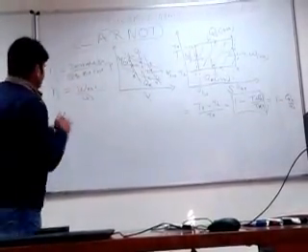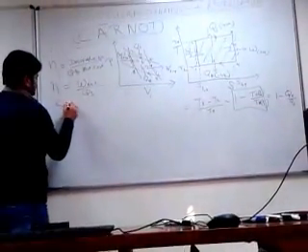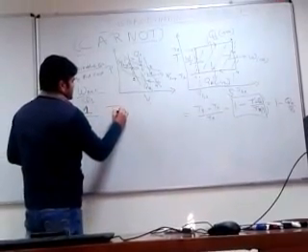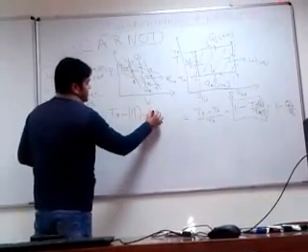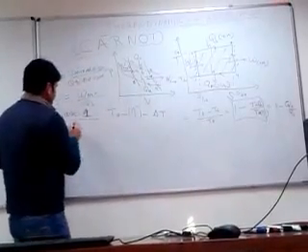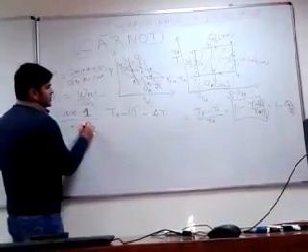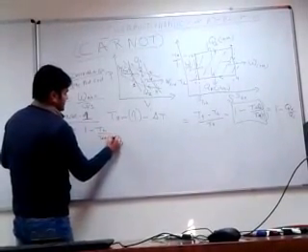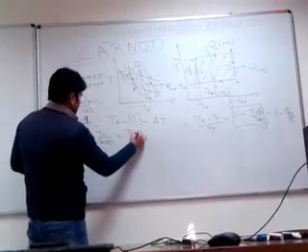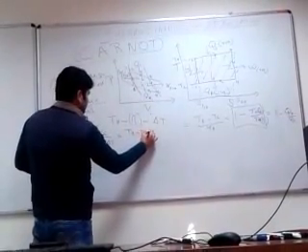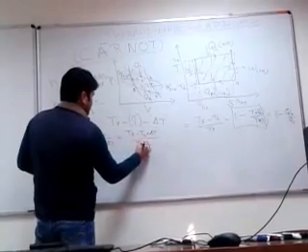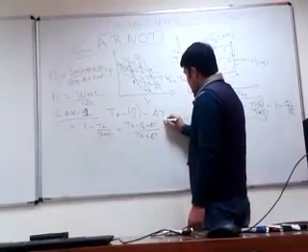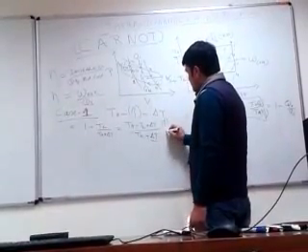In case 1, if we increase the higher temperature by some quantity, say delta, then putting this into the formula, 1 minus T lower upon T higher plus delta, it comes out to be T higher minus T lower plus delta upon T higher plus delta. So there is an increase in the numerator, but there is also an increase in the denominator.